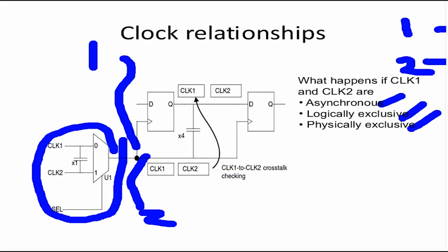If they are asynchronous to each other, PrimeTime will assume an infinite timing window. Why? Because they are asynchronous. Data on one has no synchronous relationship with data on two. So the aggressor will have an infinite timing window. That means the aggressor can come at any time, so any transition on two will always be affected by the aggressor. Always. This is what asynchronous does.